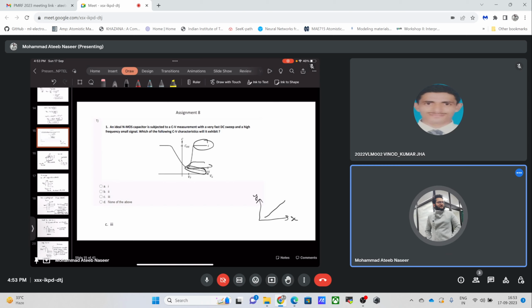So the depletion region increases, thereby uncovering more charge centers, as a result of which the charge balance occurs and we get the overall charge neutrality. This results in deep depletion and a decrease in the capacitance since the depletion width has increased.